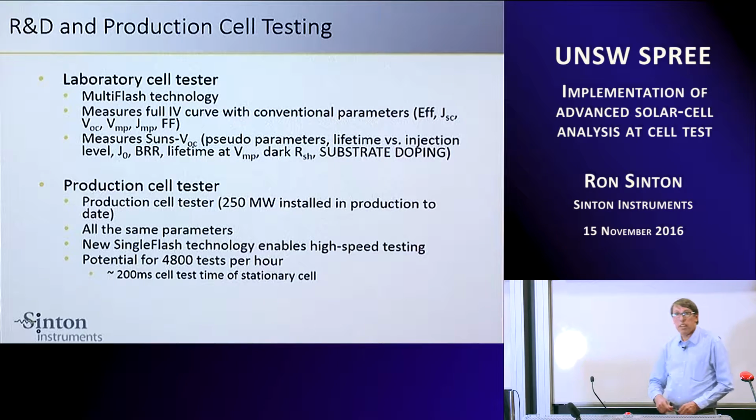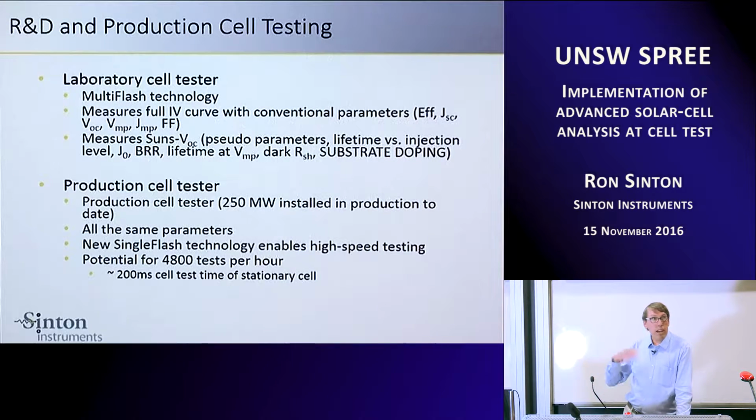I'll talk kind of interchangeably about results from two of our tools. We have a laboratory cell tester that uses a multi-flash technology. And what it does is it measures both the full IV curve with all the conventional parameters and the Suns-Voc curve as well, which has all the pseudo parameters, lifetime versus injection level, lifetime, J0, all these things. And in particular, what our tool does that isn't commonly done is that we measure the substrate doping. So I'll be coming back to this time and time again because it's really a highlight.